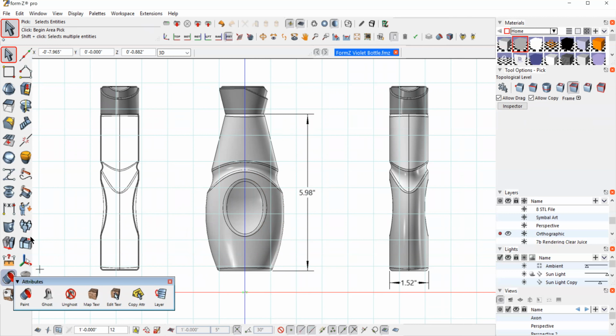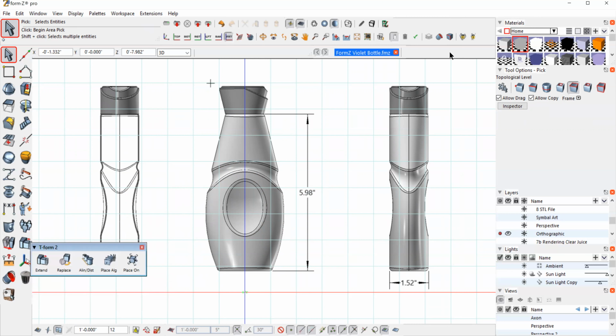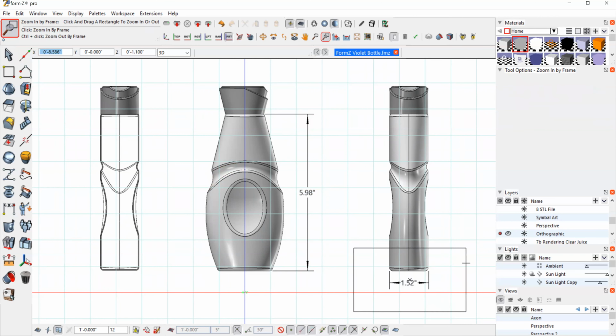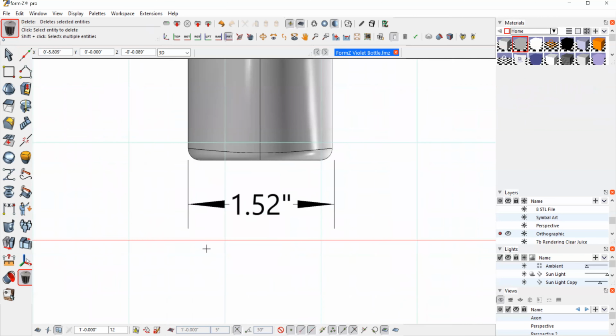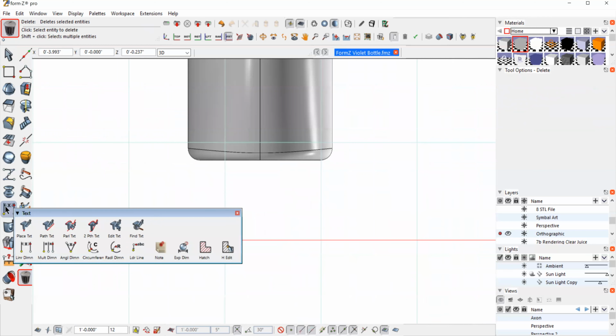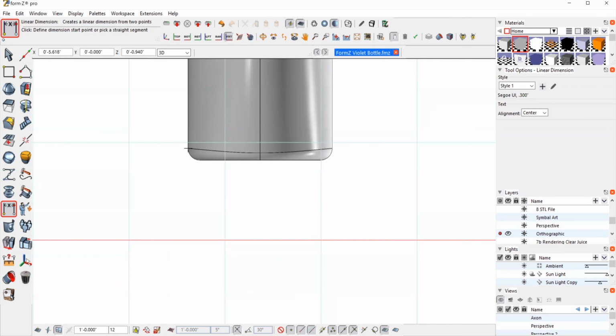Another way to do it, it's a little bit of a workaround, but it gives you a little bit more flexibility. So I'm going to show how to use a leader line and why you would use that. Let me do this dimension again, and I'll show you another feature. If you want to do a dimension like this, and I'm going to leave it selected here in orange, I can come over here and I have some options.